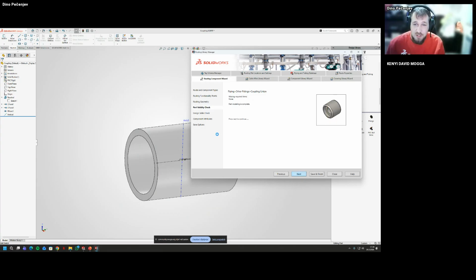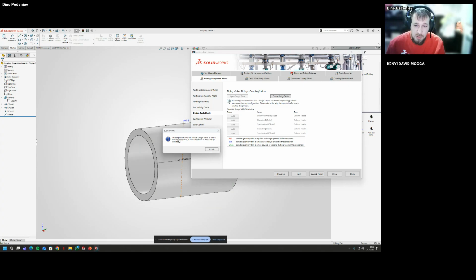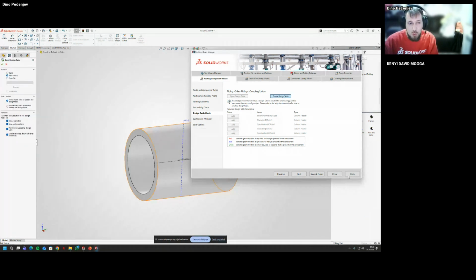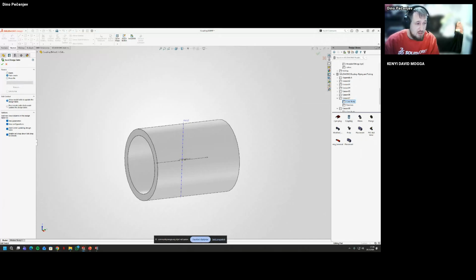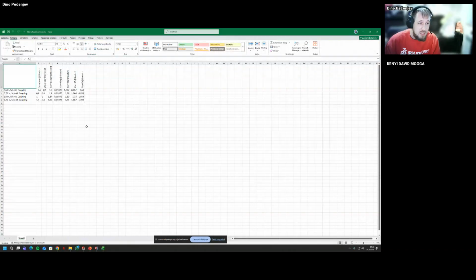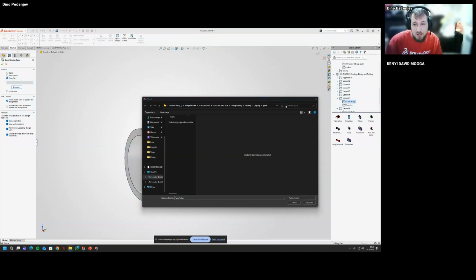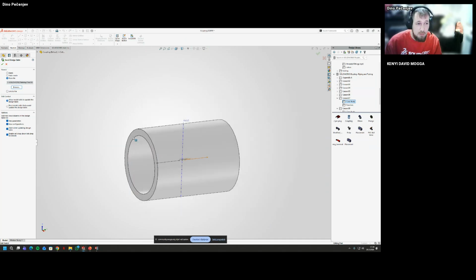Part modeling is complete. Next, if we want to open this up, this component does not have design tables for different sizes. Maybe you have specific needs, and you don't need different sizes to utilize all the configurations, but if you need them, you will need to use it. We can create it from the file. I have the configuration table set here, so I'm going to create from the file and just use it so we don't spend a lot of time manually editing the Excel file.